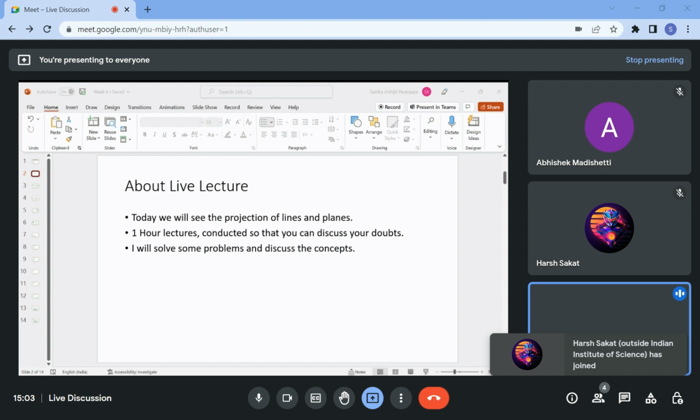To conclude this slide, the circle is the locus of all points B when line AB makes a true angle of 30 degrees with the horizontal plane. The angle with HP is always 30 degrees, but as you move along, instead of the line being parallel to VP, which is the case currently here, this position is when the line is parallel to VP.